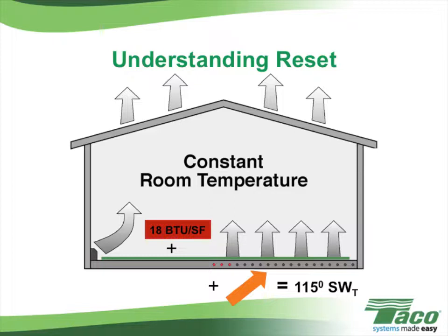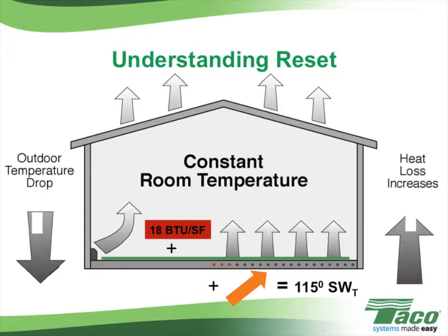Both the three-way tempering valve and the set point eye valve will provide that water temperature for you, but that water temperature will be fixed all winter long. In this case, 115 degrees all winter long. But what happens when the outdoor temperatures change?